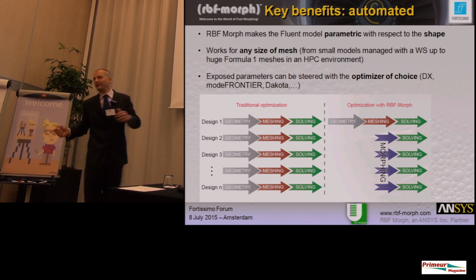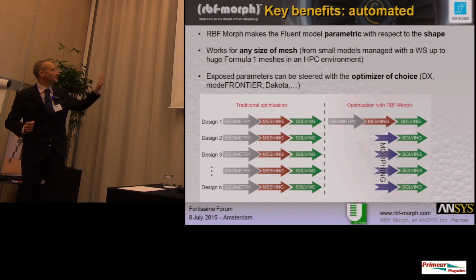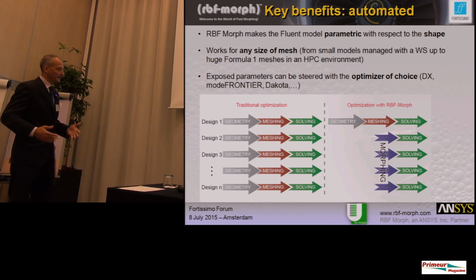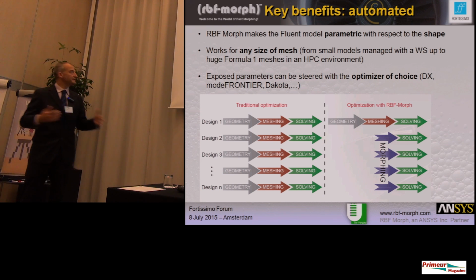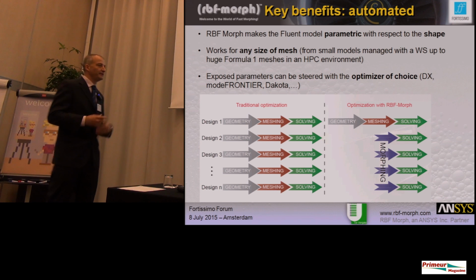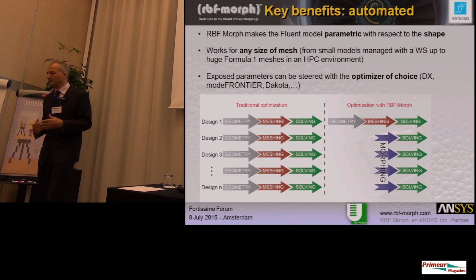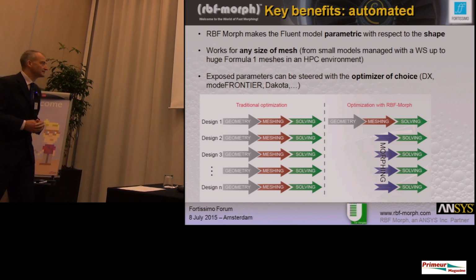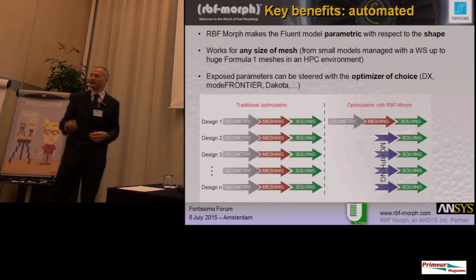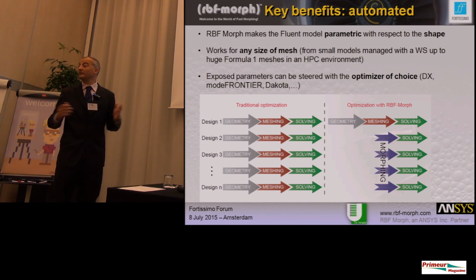why do we use mesh morphing? First, this image allows me to explain. Usually, the workflow requires a geometry, a meshing stage, and then a solving stage. The geometry processing, the featuring, and meshing could be a costly part of the process. Using mesh morphing, we do it once. All the other variations can be quickly obtained by morphing and in a fully automated fashion.